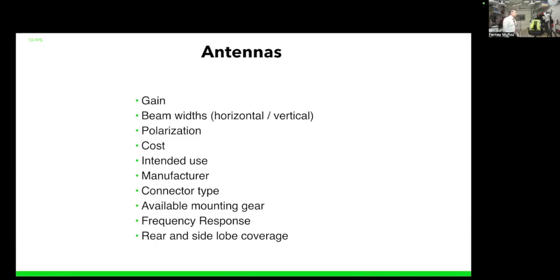There's N-type connectors, there's BNC connectors, there is RP-SMA connectors. There's all kinds of connectors, and you have to make sure that you have the right connectors for it. Now it's more work because you have to install the antenna and the bracket, and you have to mount the AP and the cables and the connectors and make sure that they are twisted correctly, that they are installed properly. All those things have to be talked about when you're doing design, and see which type of antennas. There are some antennas with leads for 2.4 and 5. There are also for 6 gig. There's all kinds of different connectors. All of those are now part of the consideration. What's the main lobe where you're going to be sending that, and how much energy is bleeding on the side or on the back of those antennas.